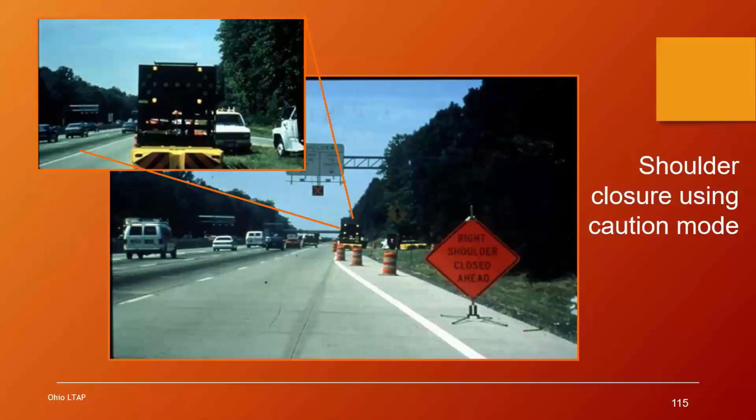So it was morning rush hour, and they had the arrow turned on. And just as I said, people thought that they couldn't use the right lane, even though they could. And so during rush hour, that eliminated one of our inbound lanes and turned I-70 into a parking lot. And of course, there were several rear-end crashes that go along with that.